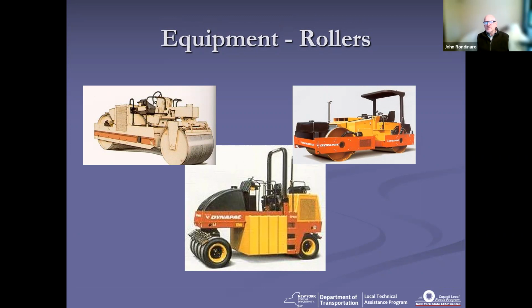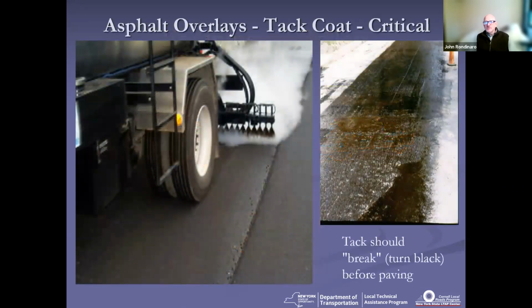Your vibratory is our typical breakdown roller, and either the static or the pneumatic tire are used for finish rolling. In terms of asphalt overlays, one of the key overlooked and underappreciated activities we need to perform is applying tack coat. It's critical to getting a good paving product.